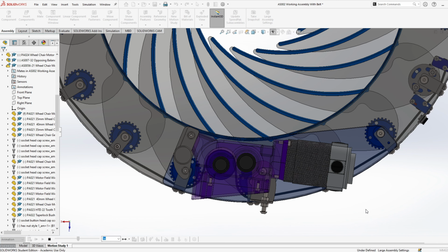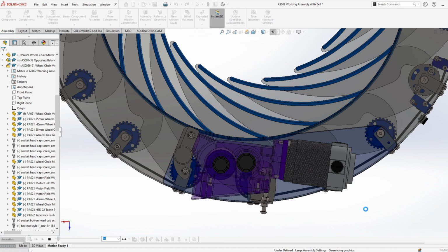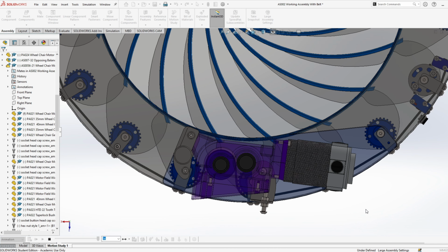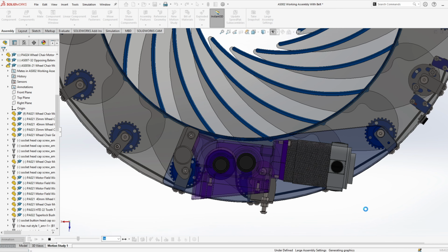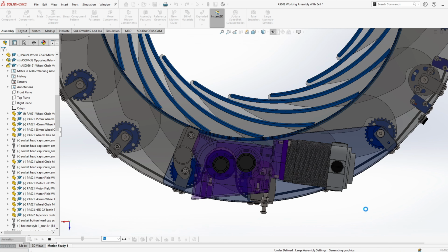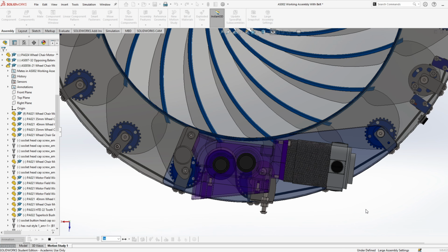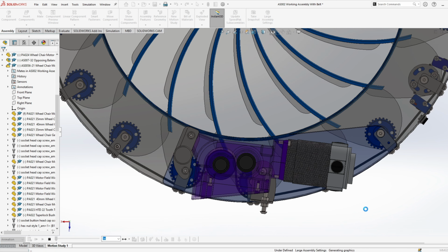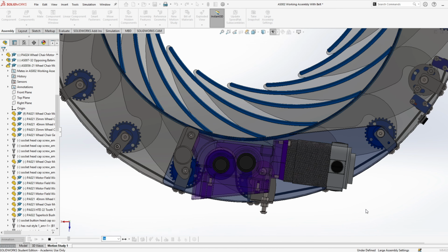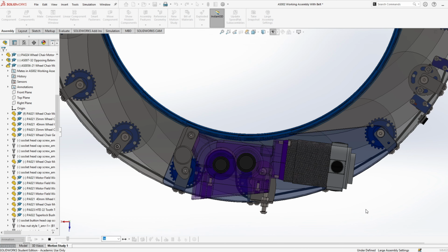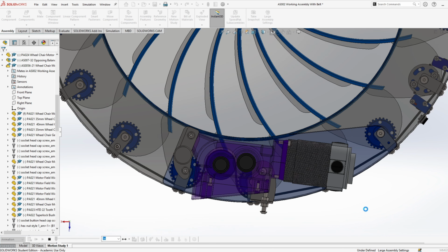Okay, so this timing belt seen here is now switched to a double-sided belt at a new determined length of 2,875mm, which is required as we are now working on the other side of the belt. This design allows pre-adjustment by mounting the motor and the gearbox at an adequate angle with respect to the motor shaft and the neighbouring two gears. This belt size also couldn't be sourced, or anything near it, worldwide, but we will get into how I overcame this soon. For now, let's keep focusing on this end of the Aperture.